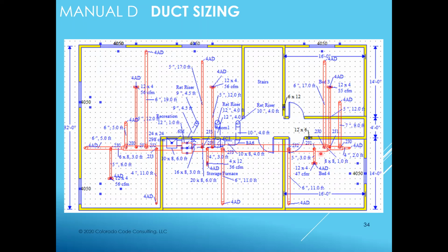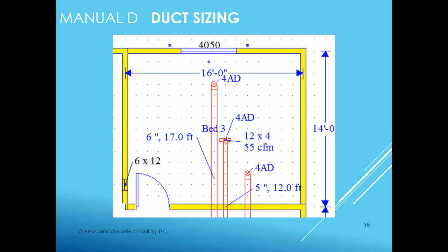So this is why the trunk reductions are important to see on the design. And if they are in design, make sure that they're out in the field, because, right? Now, if you had 2 more, 3 more added to this bad boy, serious stuff, huh? Might not see hardly any air coming out of here. Yeah, so trunk reductions are hard. And you don't want to get an 8.5 by 11 like this, where it's all scribbling, you can't see. They can do 24 by 36s, so you can start to see stuff that's clear.